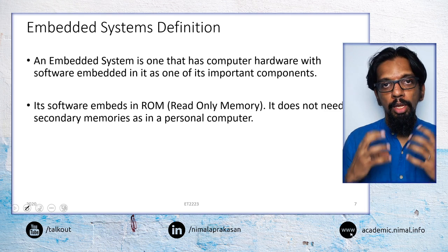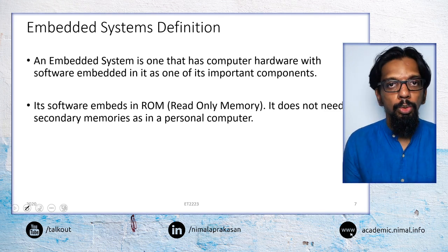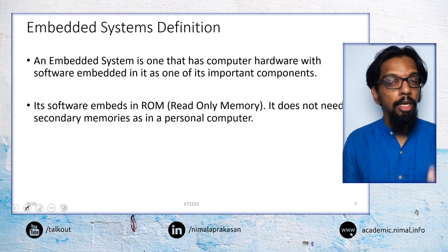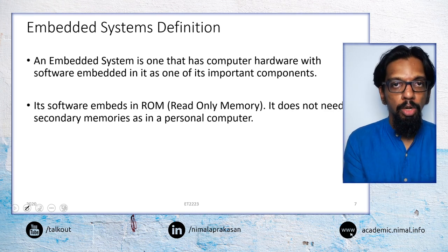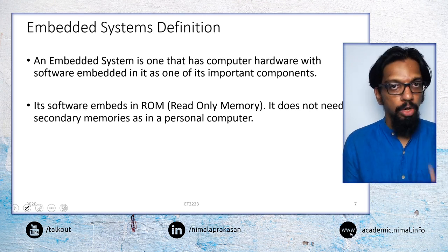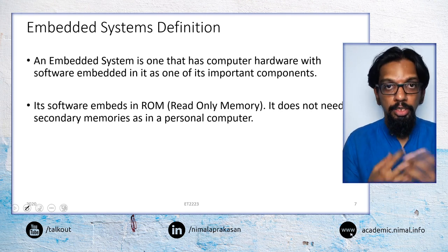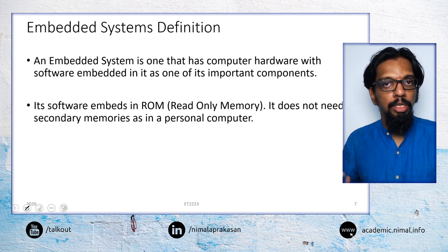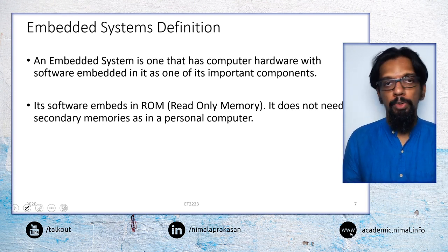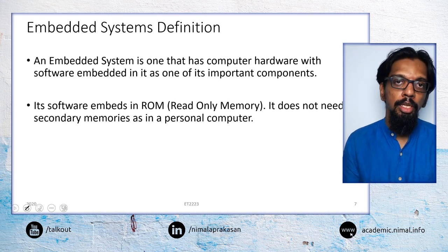It is going to have software, but that software is going to be in many ways permanent. It is not going to be replaced as frequently as we may do in a general purpose computing environment. In many of these embedded systems, it is commonplace to find this software loaded into what is called a read-only memory, because there is no expectation for these things to be modified or updated in a regular fashion as in a general purpose computing environment. We may also not have a typical storage device like a hard drive or any other sort of external storage device in such an embedded system.